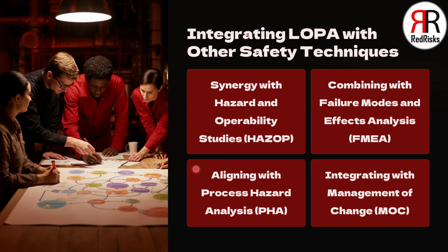LOPA builds upon the hazard identification and consequences analysis performed in PHAs, process hazard analysis, thereby adding a layer of quantitative risk assessments. LOPA can be incorporated into the management of change process to evaluate the impact of changes on the existing layers of protection.